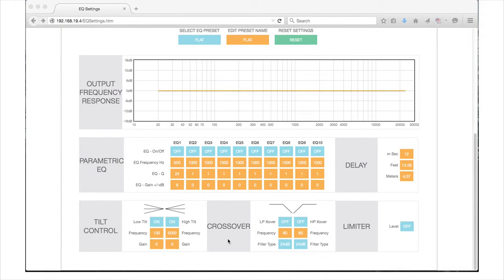In the SonArc software, we have the ability to apply independent low-pass and high-pass crossover filters. The basic function of the low-pass crossover is to eliminate the high frequencies from going to a subwoofer. The basic function of the high-pass crossover is to eliminate the low frequencies from going to the satellite. Through proper adjustments of the crossover, you will be able to achieve a seamless blending of your satellites and subwoofers.